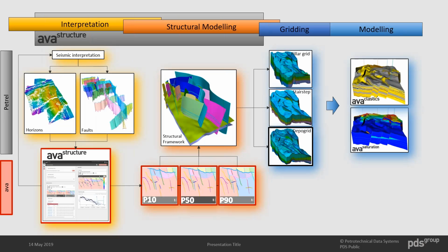Okay, that's a very good question. Obviously, the horizon uncertainty is something a bit different to what we're talking about in terms of compartmentalization. The horizon uncertainty can be incorporated through things like depth conversion workflows, projections towards the faults, which we can do, but ultimately what we want to know is where those fault connections are before we start looking at the horizon uncertainty. So when you're doing step out distances and removing the data away from there, we'd recommend doing as little of that as possible, and then building your uncertainty around that, and making sure you have the connections in place before you start flexing the horizon interpretation.